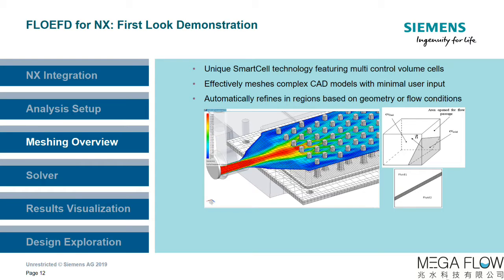Traditionally, one of the trickiest and most time-consuming aspects of CFD has been the geometry meshing stage. The fluid and solid regions are discretized into grid cells, which is then passed to the solver for solution. It's normally at this stage that requires the geometry to be simplified for meshing or simulation compromises made for the sake of solution time.